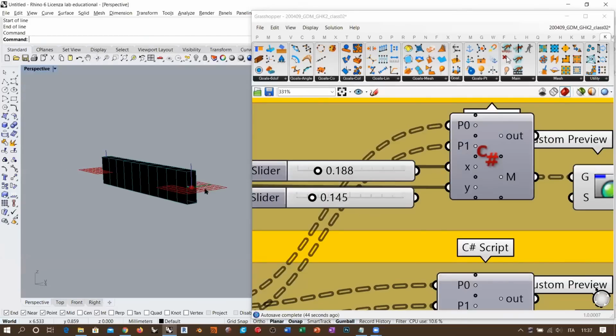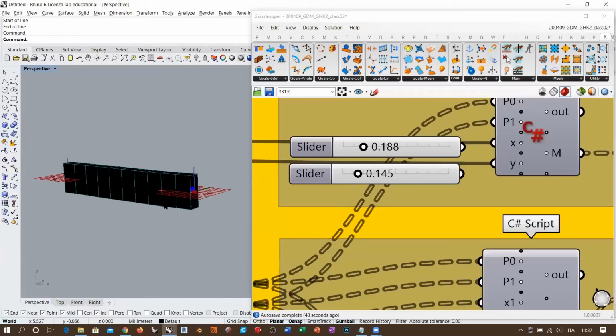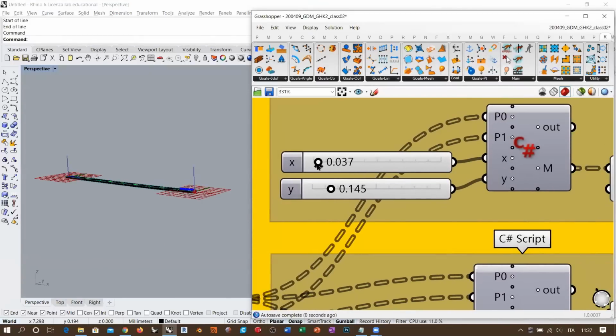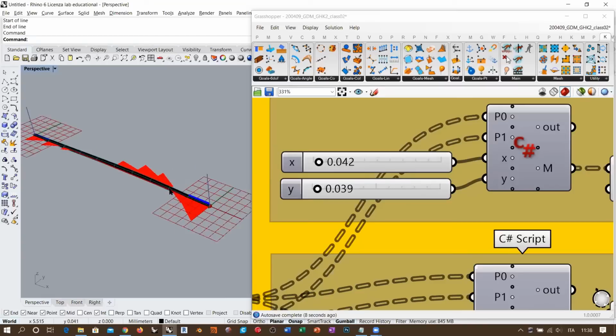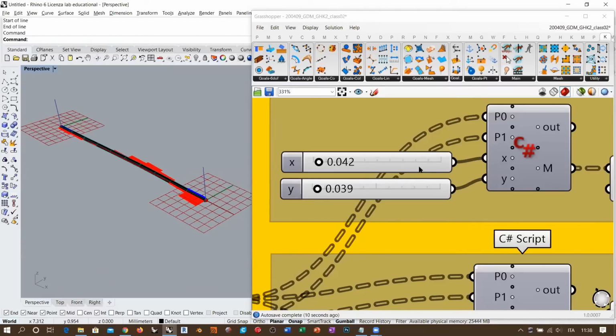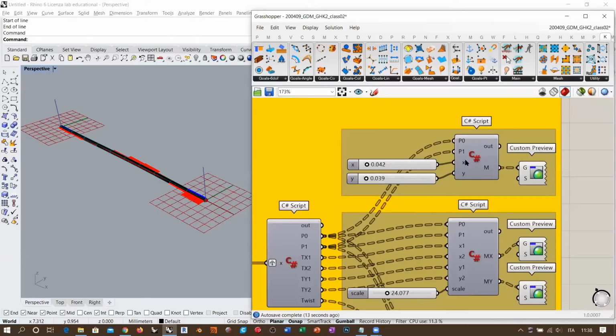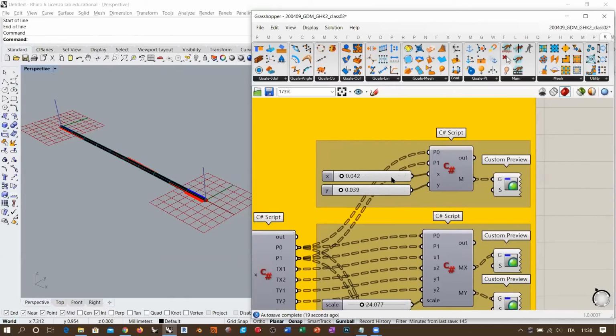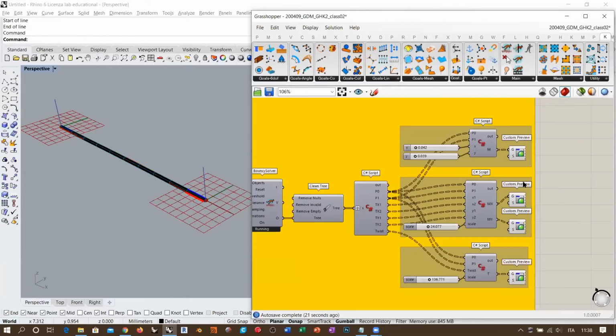So if you have these, for example, and you start working with this, let's say, deformation, you see nothing because the graphic is inside the body of the beam. So I would recommend that you eventually, after the simulation, work with smaller geometry. Also, you can decrease this to very small values, because this will allow to understand exactly what happens in terms of stresses. So that's why you have this additional definition for the geometry of your beam. It's weird from a realistic representation, but at the same time I understand it completely, because eventually you want to see what happens in terms of stresses more than deformation.